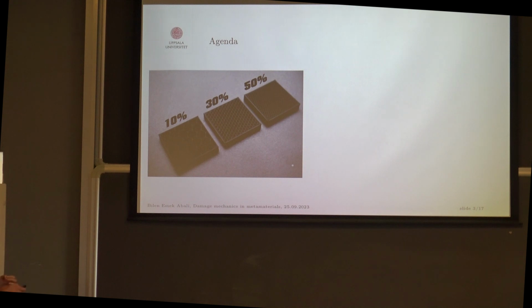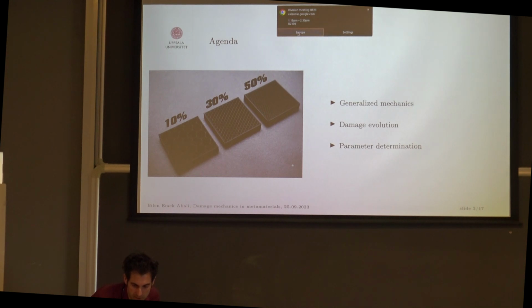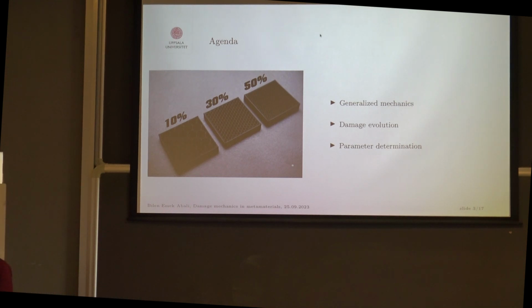Now, even at 30 or 50%, I would never use 30%, but if you want to use that, have a look at the microstructure. It's a repeating pattern, of course, and the characteristic length of the microstructure and the characteristic length of the whole geometry are of the same order of magnitude. So we cannot still use linear elasticity or Hooke's law that we normally use. We need to invent something more generalized, and that's exactly the topic, as we all know. Strain gradient elasticity is something useful that we can use as a homogenization tool here.